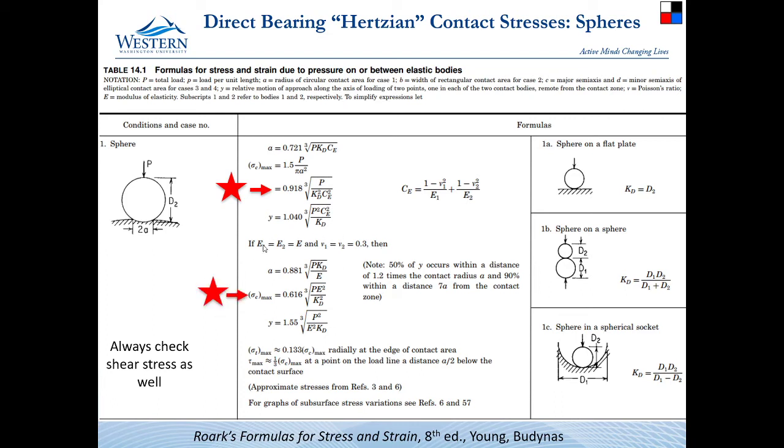And then we take that maximum compressive stress. If we were doing it in a case where the E's were equal and the Poisson's ratios were equal, so if you have two steels, this will be really close. It's not actually always a bad assumption with aluminum either, though depending on what aluminum you're using, the Young's modulus can be quite different. So anyway, if you had this special case, then you would use this equation instead.